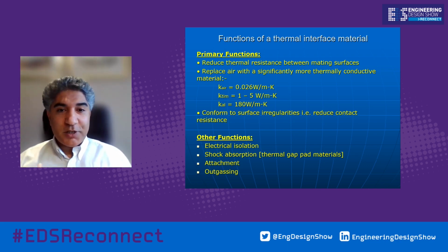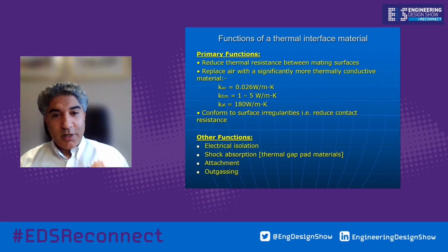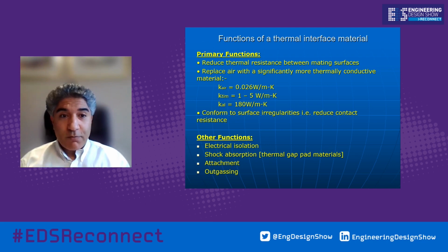Another function of a thermal interface material could be electrical isolation. The gap pads could offer some shock and vibration dampening, cushioning, and attachment of a heat sink onto a heat generating component or a system. And obviously some of the materials can provide low outgassing if you're concerned about outgassing or silicone leach.